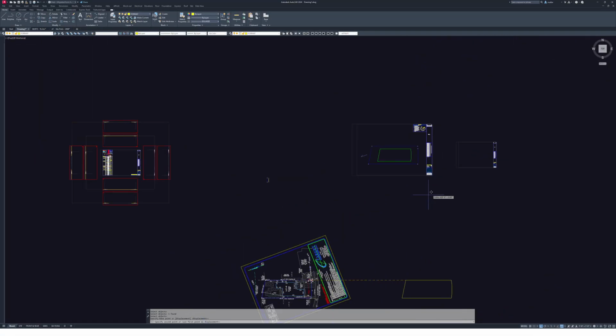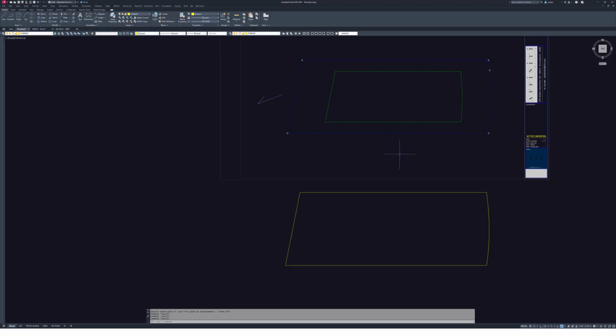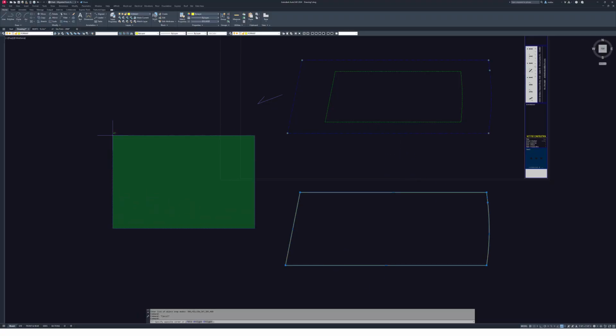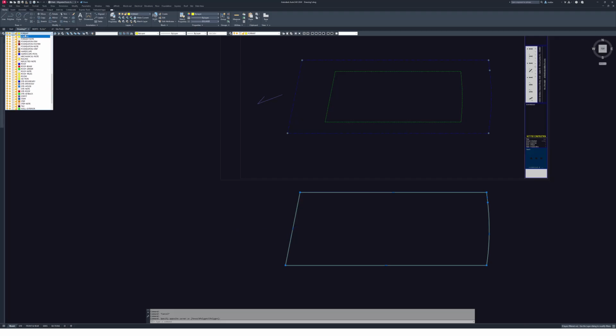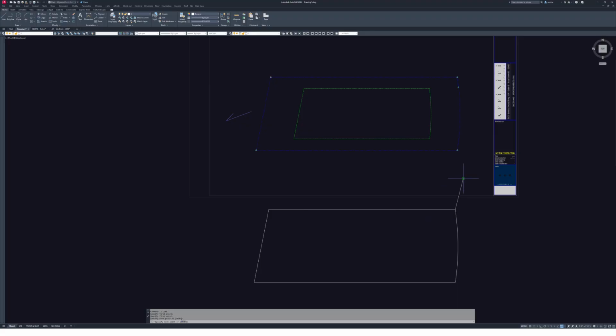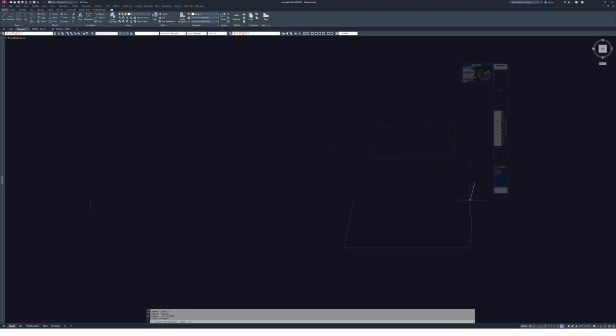So now if I move this up over here, and we do the same thing, I'm going to put this on my 0 layer. So we'll go 0, and I'll draw this line, Control X, Control Shift V. I'm going to double click, copy, orient to rename this, paste the old name, and then this one we'll just call Survey 2, just for the heck of it, RFE to reference edit, add.